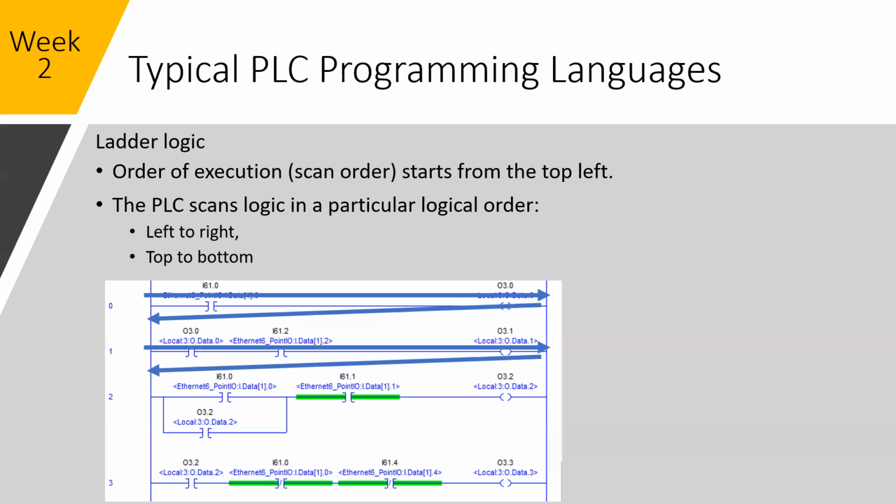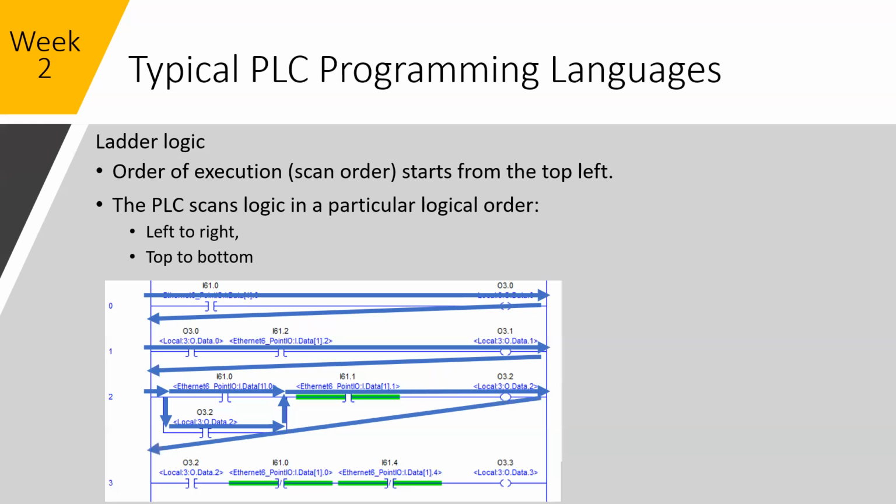You'll see here that this branch, they call these branches. If you're familiar with Boolean logic, this would be an OR statement. So if this or this is true, then what will happen is it'll scan to the start of the branch. It'll evaluate the first bit in that branch, then it will evaluate the next branch down. If either one of them is true, then it will continue on to the end of the branch, or that ladder, and then it'll skip down and continue.